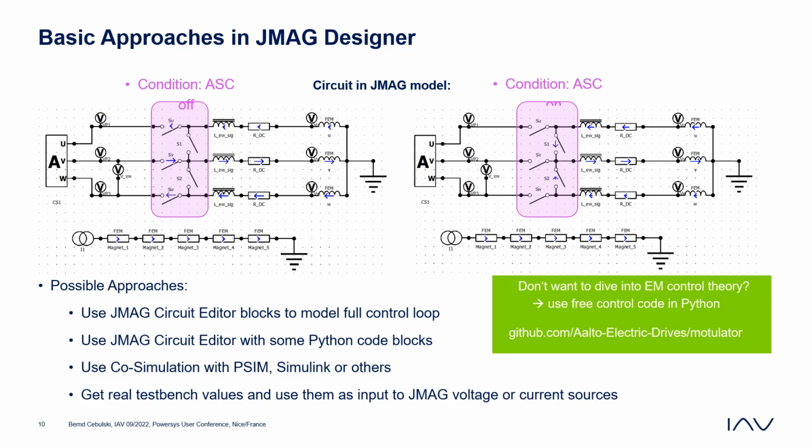There are several possible approaches or simulation techniques you can use. You can use the circuit editor blocks to fully model the control loop, like in Simulink, everything graphically controlled. This is an approach for easy control circuits, it can be done, although in my opinion, there are still a few blocks missing in the circuit editor to do this.